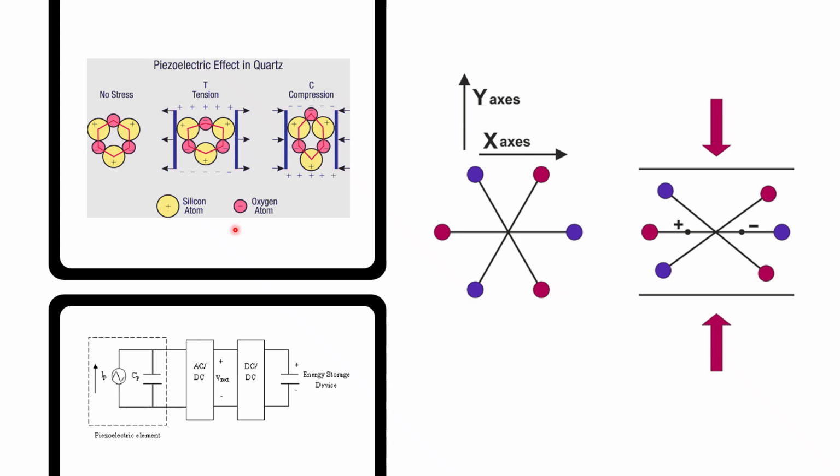When the crystal is deformed along two opposite sides of the hexagon, the structure is flattened, and the distance between the opposite vertices increases at the ends. This causes an imbalance of charges along a central axis, creating a small dipole moment. That's how the dipole moment induces a small amount of voltage across the crystal, perpendicular to the applied force. This is how piezoelectric energy is obtained, and you can see how it has been conditioned, as I mentioned in the beginning of this video.